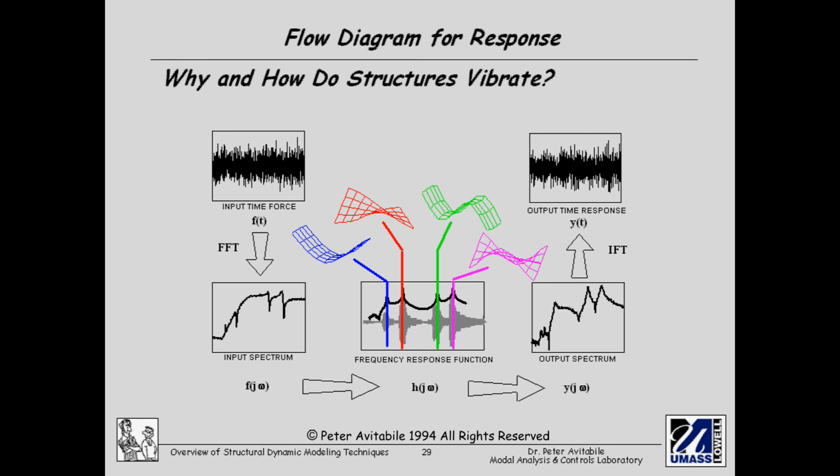Now, by taking a look at the data and transforming it to the frequency domain, I start to see things in a different light. Things start to become a little bit clearer. For instance, if I look at the lower plot here, this input spectrum, I see that now that I took this time data and transformed it to a spectrum, there's some energy that's distributed over the frequency spectrum, and I understand a little bit clearer what energy content exists at what frequencies.